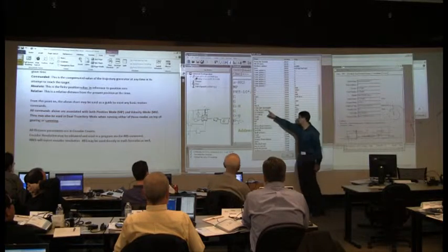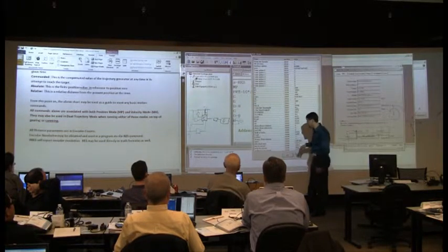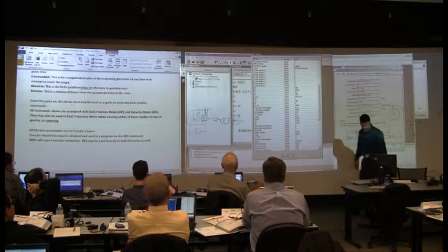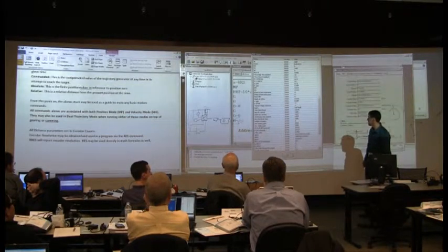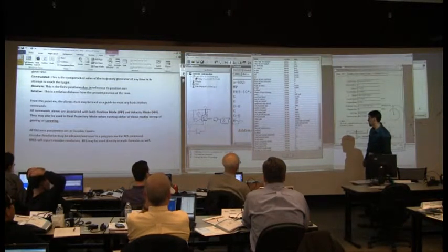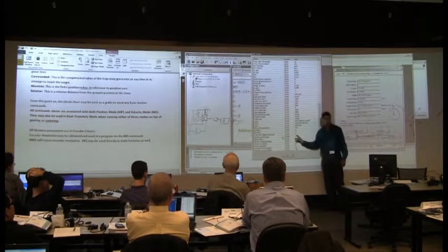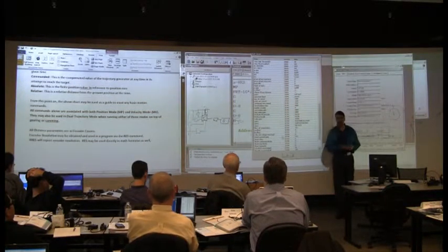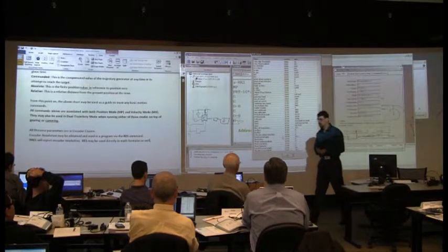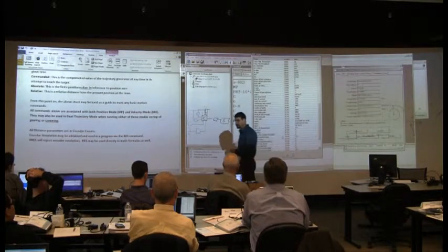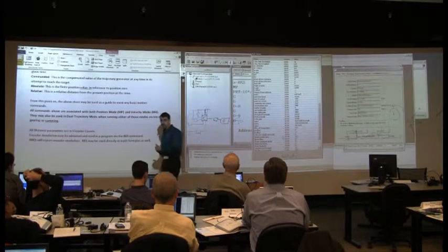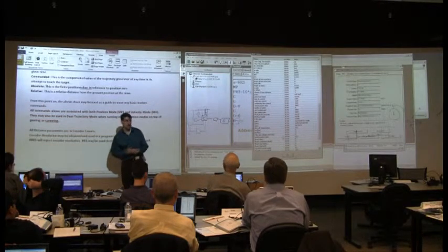You'll also see shunt enabled. This is for another product that has a built-in shunt. There's also a low bus voltage threshold. I don't know where it is. Here it is, right here, 8 volts. That's directly in voltage. If you go below 8 volts, it will also shut down. Okay, why do you think we did that? Why would we have a low bus voltage fault?